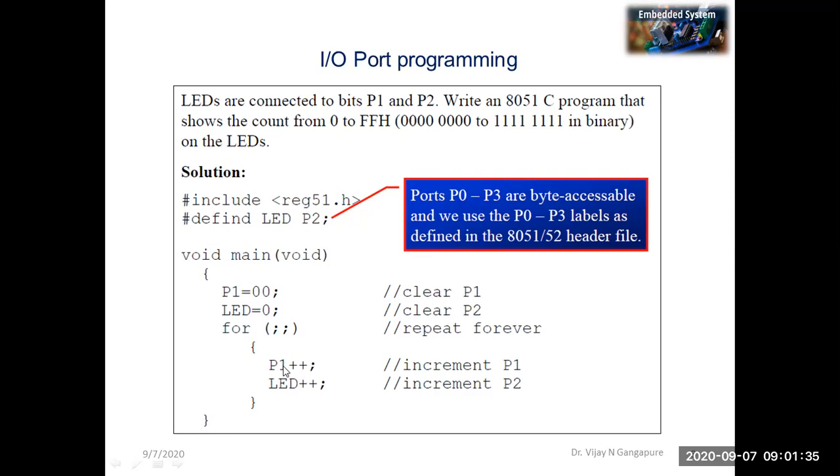Okay, in other words, what we are doing is outputting data on port 1 and port 2, which varies from 00 to FFH, and that is what was asked in this program. In this way we can program the ports of the 8051.